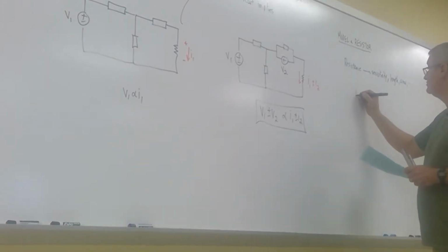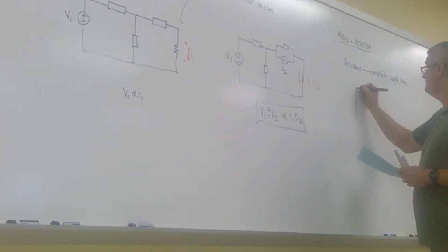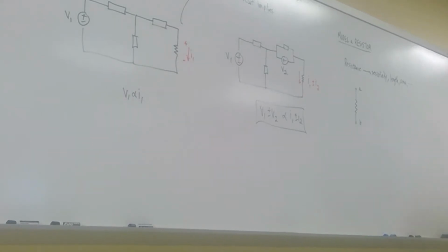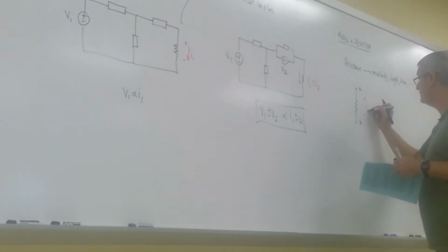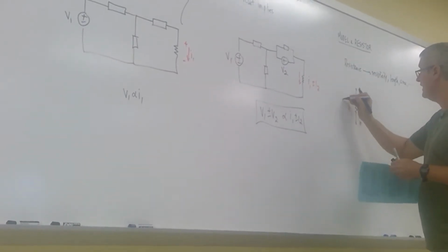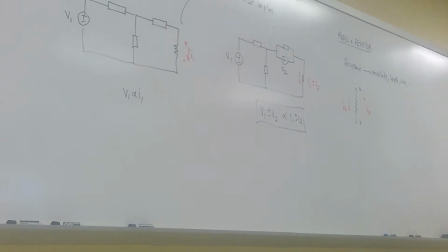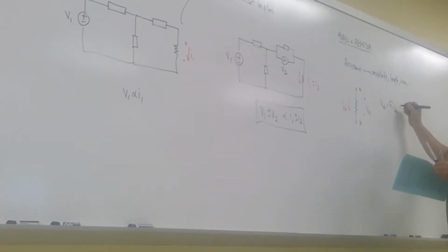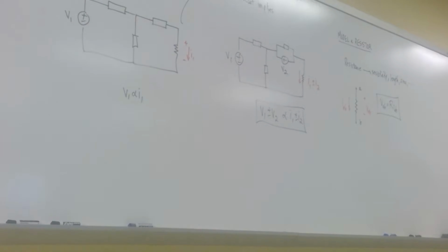So if I have a resistor, that means when I look at these nodes from A to B, and I have some voltage drop here, if I have a voltage between A and B, I'm guaranteed to have a current AB across that, such that the voltage across that resistor is given by this quantity right here. Right? Resistors are passive elements. Right? These are passive elements because they dissipate power.